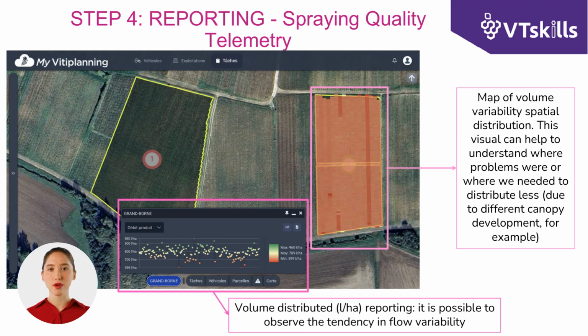For example, where deviations from the set spraying volume or untreated areas are evident, punctual action can be taken to maintain biological efficacy. In the demonstration map created, the areas in dark red where a spraying error was generated about other parts of the vineyard due to underspraying are evident, as are those portions at the beginning of the row where the operator delayed the start of spraying.